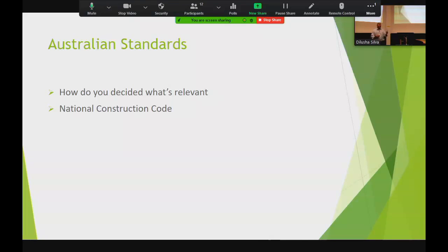Yeah? So the National Construction Code, which was also called the BCA, Building Construction Code, is a document that sets out that all buildings have to be constructed to, in terms of provisioning. So it will say in that document, life safety systems will be things such as emergency lighting, fire detection. It doesn't worry about things like power points and air conditioning. It'll worry about ventilation, fire detection, fire management type systems. But that document will then say to you, you need to provide artificial lighting in accordance with 1158 for external and 1670 for internal. All right? So you need to start at the beginning and understand where you're going.